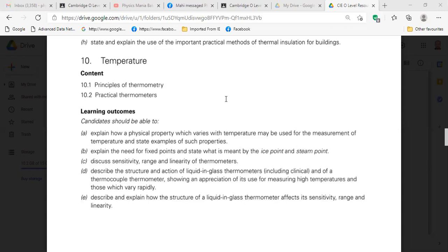From this name we understand it is one kind of resistor whose property changes with the temperature or thermal energy. So what is the property of that resistor? If its temperature increases, then its resistance decreases. Okay, so if resistance decreases, that means current will increase. It will give more reading.